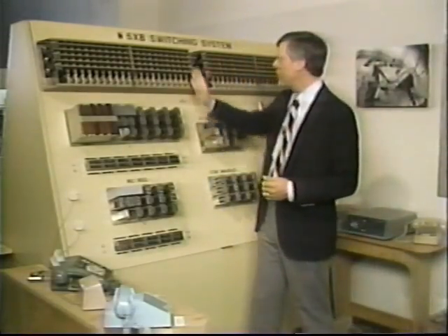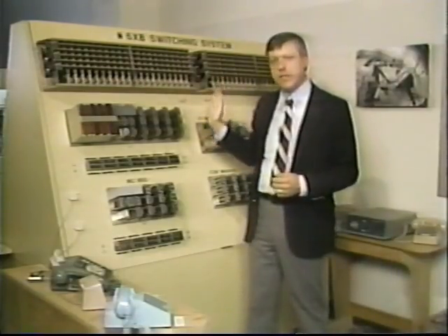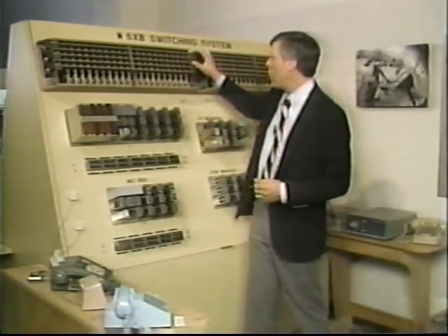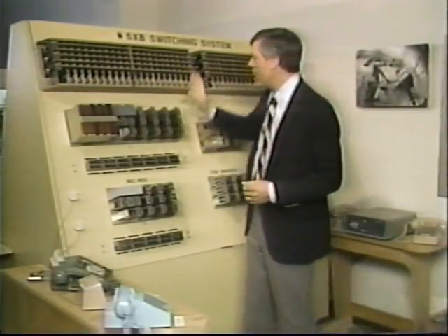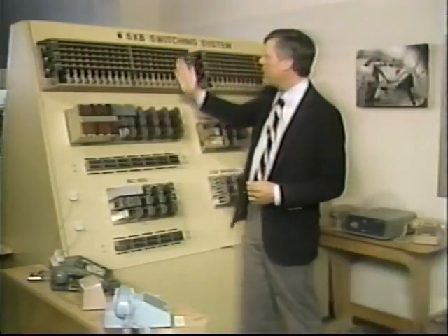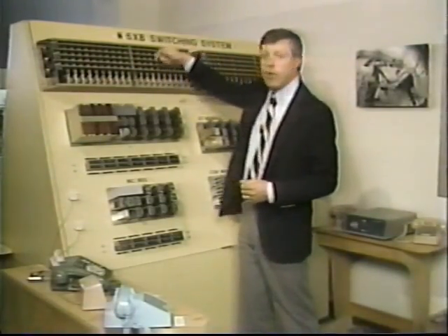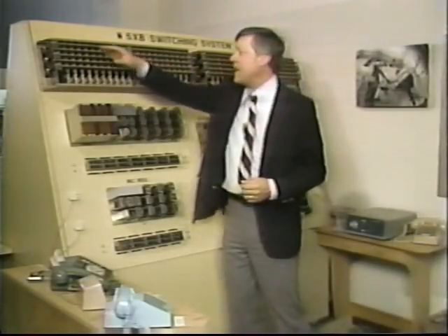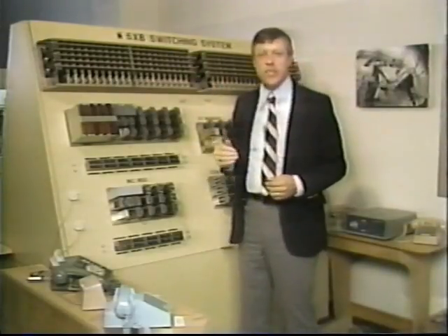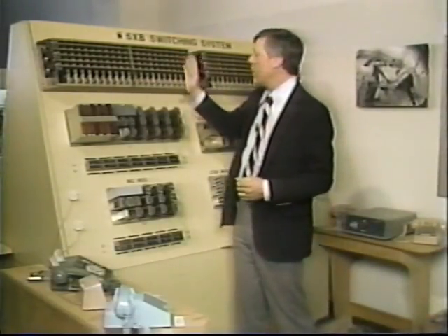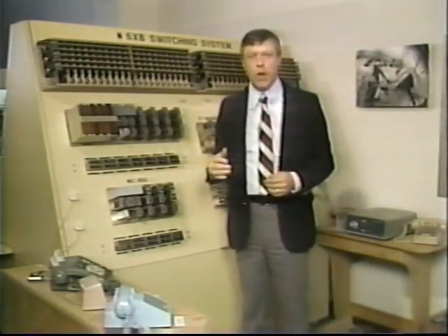Now in this particular case, there are rows of relays laid out in a matrix. When a call is placed through this type of a switching equipment, where the rows of relays meet in the matrix is where the connection's made. Now vertically, there are 5 relays in each vertical row. One connection can be made in each vertical row. Many connections can be made then across the crossbar switch at the same time, so that through one crossbar frame like this, multiple calls can be in progress.